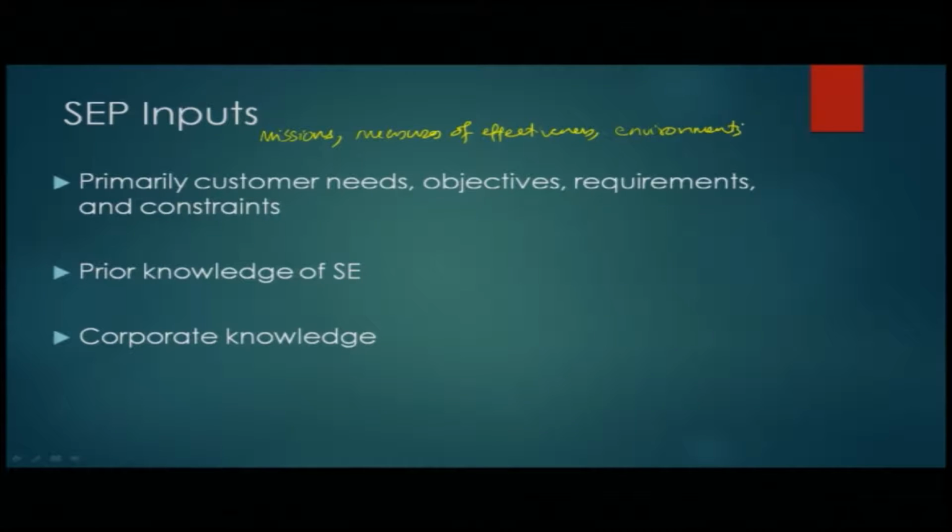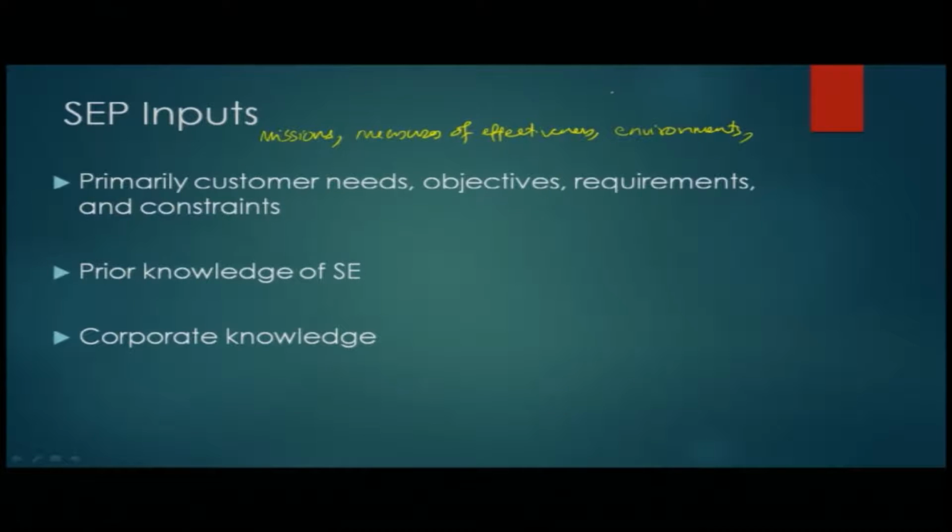Environments. This could be operational environment, this could be some other environmental criteria. For example, when the UAV development happened, the customer came back and said you should be able to operate it in high altitude area. Well, high altitude area is a very loose statement, but that's an operational environment requirement. So you need to now define what is a high altitude area, what height above mean sea level. So in this case, we finally ended up deciding X feet above MSL, it should be able to take off. That was decided by the discussions with the customer.